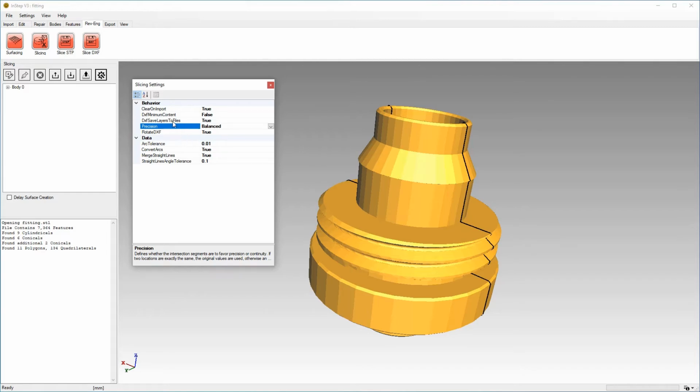It should also be pointed out that we can have each layer or each individual section exported to a separate file if you can find those, or if you should try and keep them all in the same file. We're going to turn this off so it writes all to one file. The minimum content really defines whether or not the output DXF file contains header information and so on, or if it's just meant to contain only the geometry. Generally going to want to turn this off or leave it off, as most applications expect some amount of content.